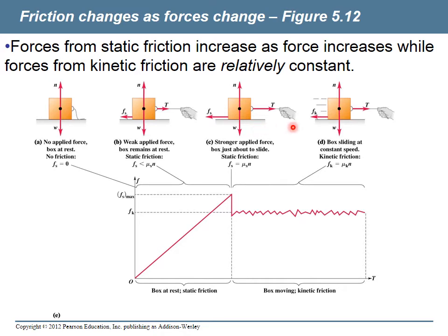If I apply more force, it's going to be on the verge of moving. Right before something starts moving, that's when the force of static friction is equal to the coefficient of friction times the normal force. This is the one we'll focus on mostly because we'll be concerned with when it's about to move, right? Maybe sometimes I'll give you a force and I'll say, well, is it going to move or not? If I have a 500 Newton block and I push on it with 10 Newtons, is it going to move, right?